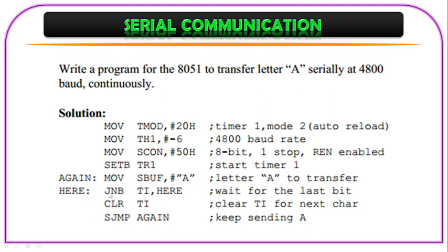So jump if no bit TI. TI is checked until it becomes high. Once it becomes high, you come here and clear it and then do it again, because A has to be sent out continuously. So jump to again. So this is a very simple program to transfer A.